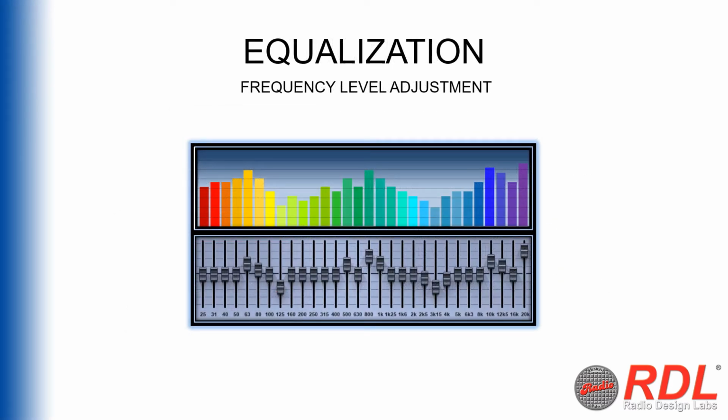Equalization, often called EQ, is an audio effect used to adjust the levels of different frequencies or pitches in an audio signal. These adjustments alter the collective tone of a signal's sound to either improve its tonal quality, or to adapt it to a sound system with frequency limitations, or to help it blend in or stand out amongst other signals. Equalization is available as a standalone device called an equalizer or an EQ, or as an integrated feature in other electronics such as audio mixers and DSP units.